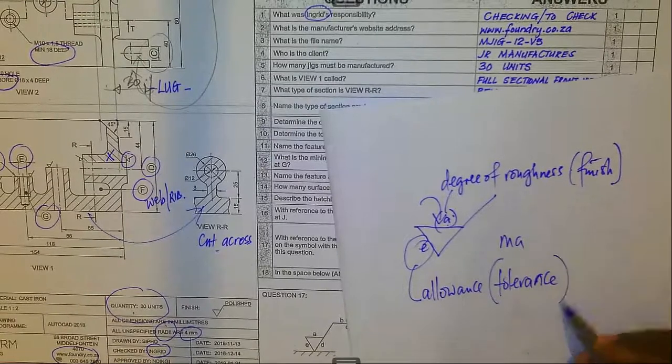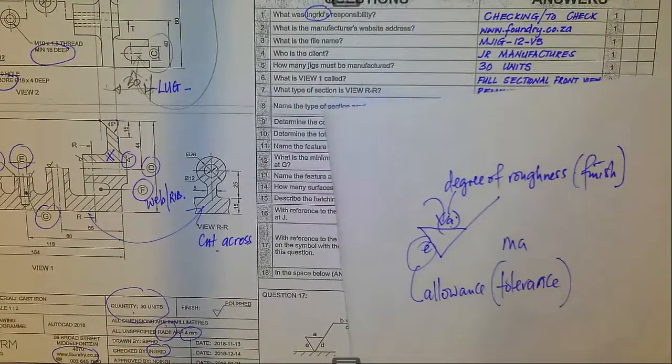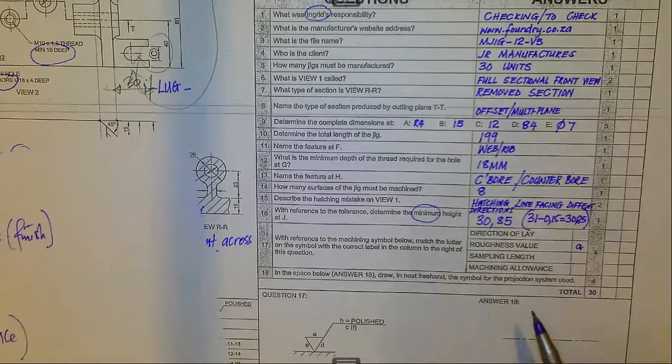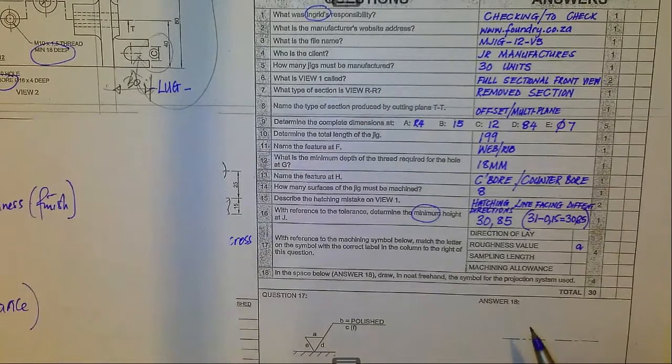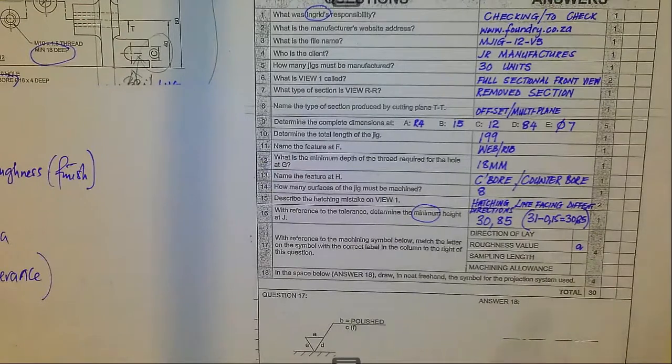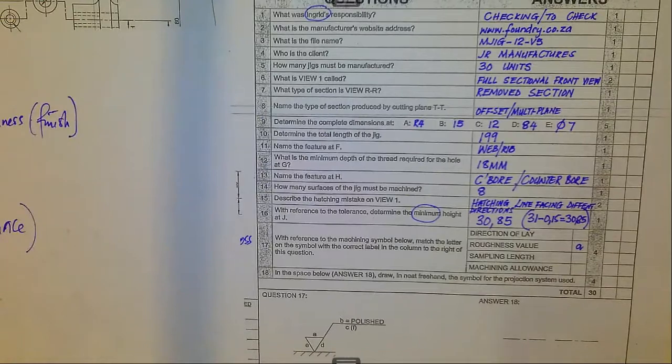This tolerance is to say that whatever you do, make sure you are able to leave at least, say, 2 millimeters, 3 millimeters in terms of the machined parts. Technically speaking, when we are talking about machining, we are talking about the removal of excess material in order to come up with the desired shape, in terms of an engineering artifact or a component.